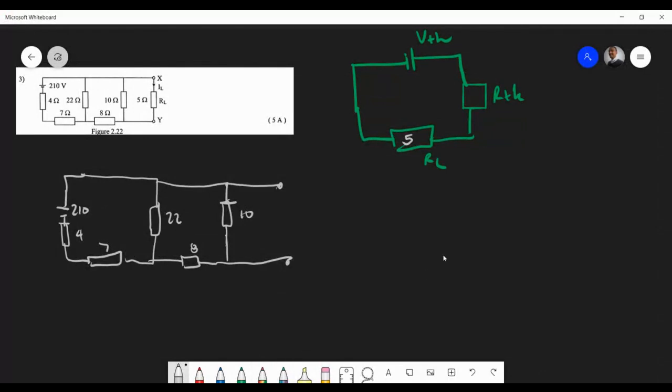Okay. So looking at this, we have no current in the open branch, so this one and this one are in series, right? So the first thing we have to do is take the 18 and 10 in series, but this will be in parallel. So this one and this one just is 18 ohms. Then that and that will be in parallel. So 22 ohms and 18 will be equal to 22 times 18 over 18 plus 22. You should get a resistance of 9.9 ohms, right?